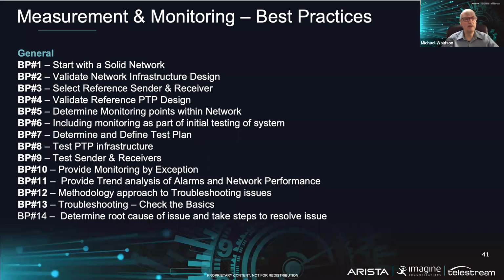Once we've installed our system, we're going to be monitoring by exception. So not getting a whole catalog of errors, but looking at specific errors that are given by simple red, green indications, and then working down through that process to pinpoint the error, troubleshoot the problem and resolve that issue. So we're taking methodologies to identify problems, troubleshoot those problems, and it's always important to check the basics, to remember those fundamentals, and to make sure that you are validating those fundamentals.